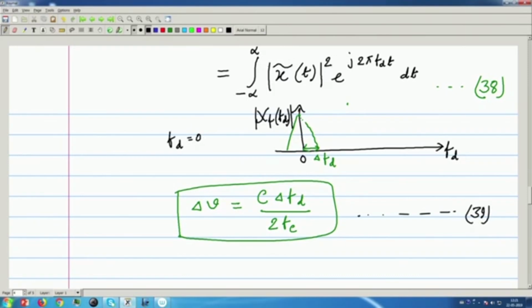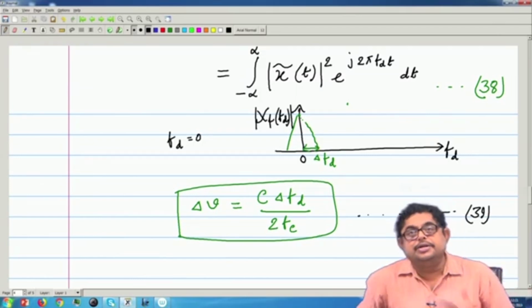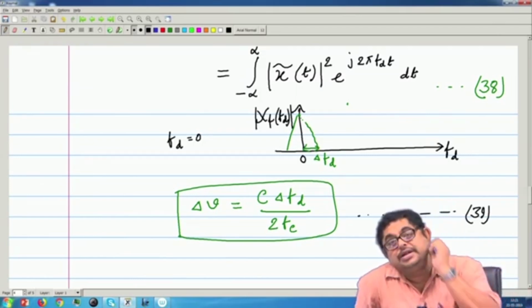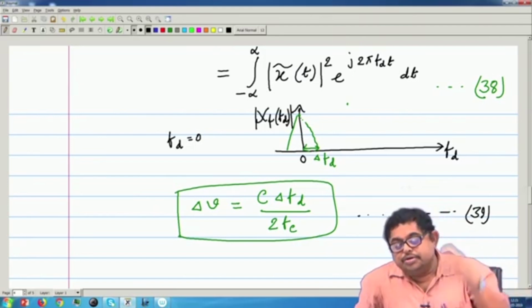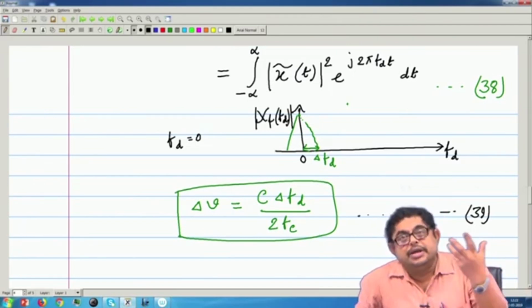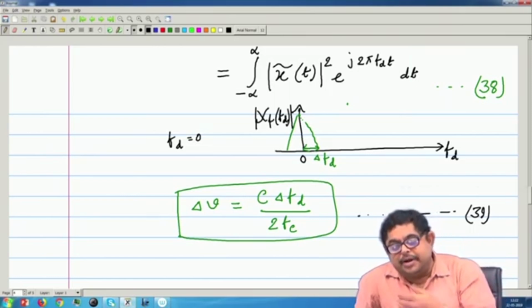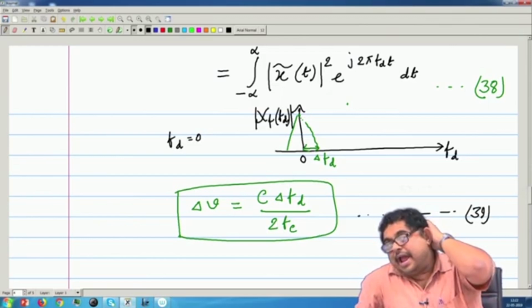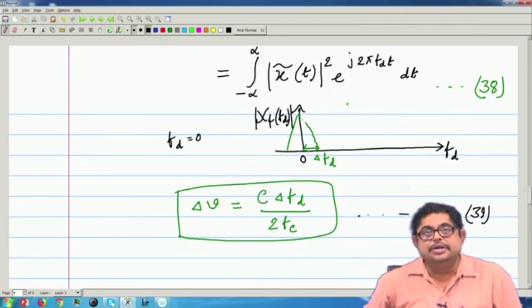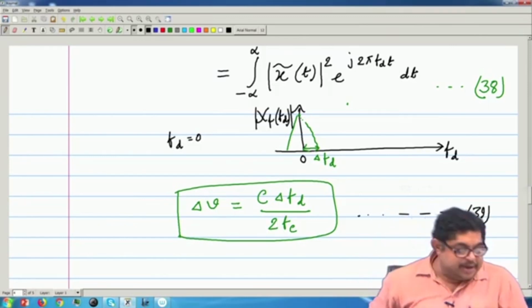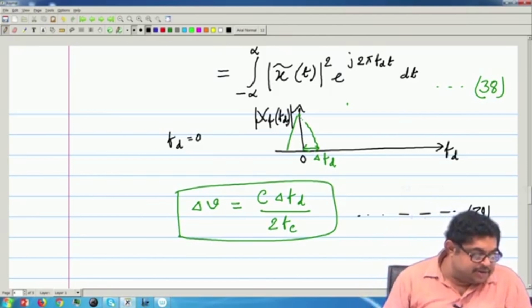So, again the Doppler resolution will be determined by this. So, now you can choose, because everything depends on the shape of x t. So, x t designers can choose, so as to give both this range ambiguity function and frequency correlation function a sharp peak at the respective 0 values and a very high roll up, so that the width is small.